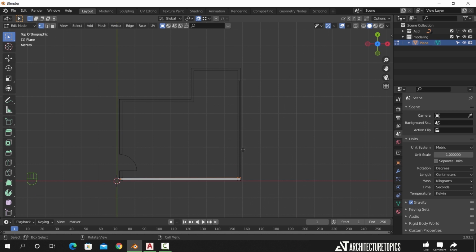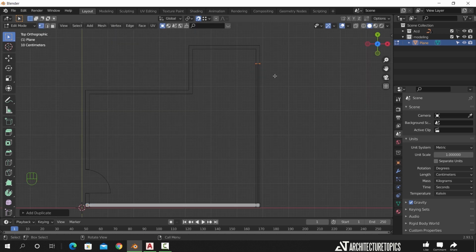On this wall, we have a window. What I do is hit Shift D to copy the selected vertices and snap them to the top window's corner. After that we can extrude them again and again on the right axis until we cover the walls on the drawing.